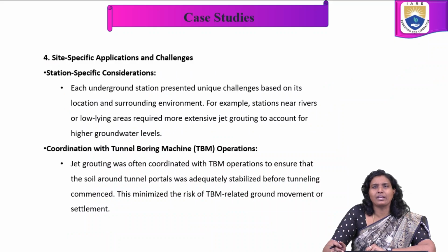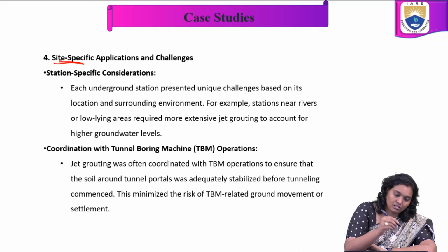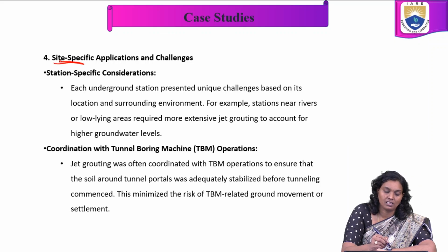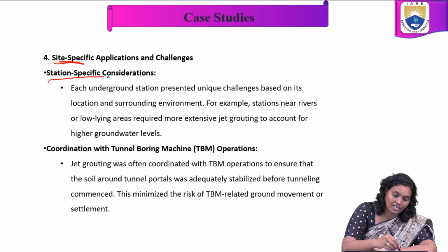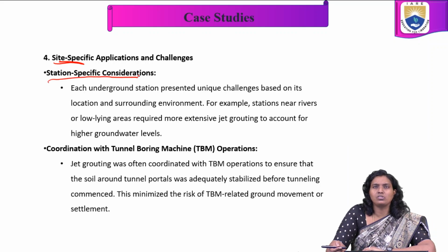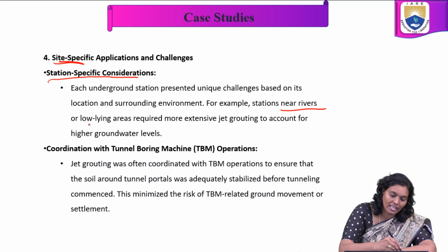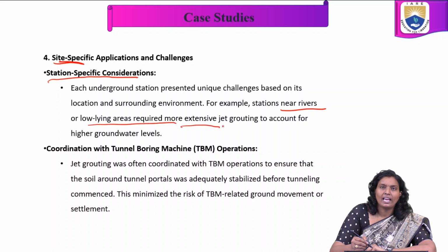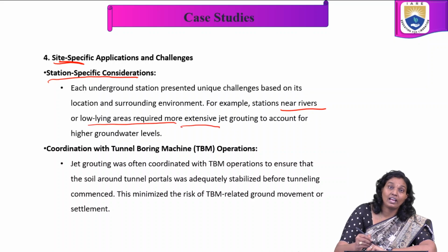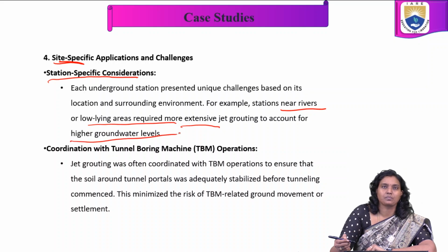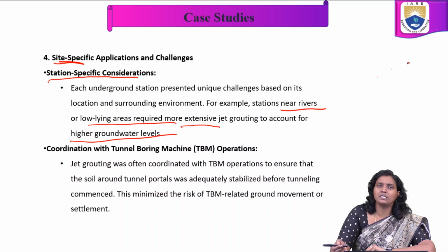Now, what are the site-specific applications and challenges? In the station-specific consideration, each underground station presents unique challenges based on its location and surrounding environment. For example, stations near rivers or low-lying areas required more extensive jet grouting to account for high groundwater levels. So it depends upon the soil conditions and where it is placed.